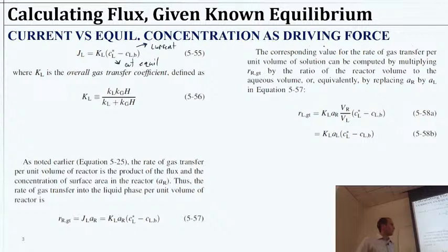All right, so another thing to keep in mind, this gas transfer is effectively a rate per unit volume. And the concentration of the surface area itself, this AR, is key. So in this case, that rate of gas transfer is going to be driven by this overall constant times the surface area times that differential, if we want to get the rate instead of a flux.